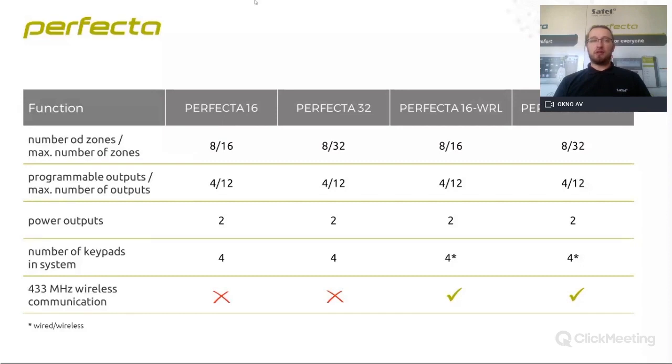There is one exception. This is for the key fobs. You can connect an INT wireless key fob from the Integra panel module. So you are able to use it, but not for sirens, keypads and detectors. For those, you will need to change the panel to WRL.